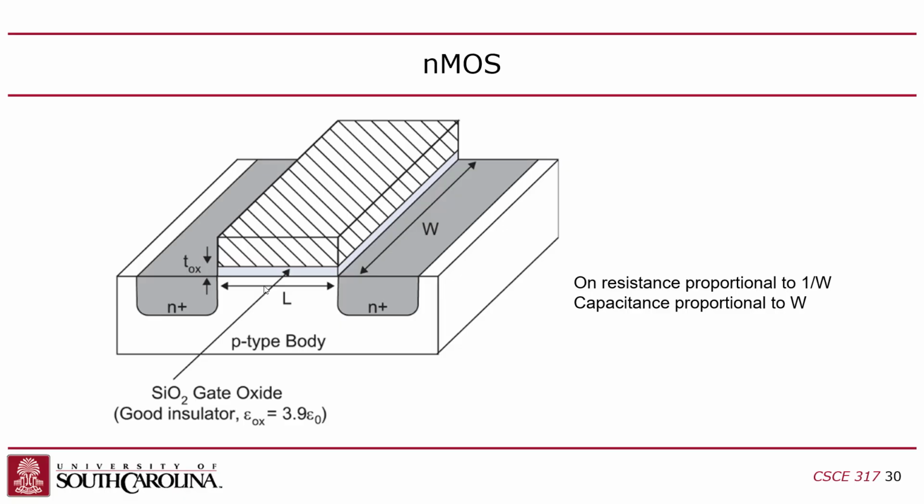So as I mentioned, typically the minimum width is about 10 times the length. So if you have a 4 nanometer transistor, the length is 4 nanometers, the width is 40 nanometers, right? But as a designer, you can increase the width, and often designers will do that. So they always keep the length minimum, always. You never make the length non-minimal. This always has to be the minimum feature size that the photolithography process will allow.